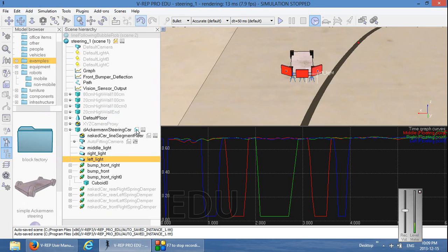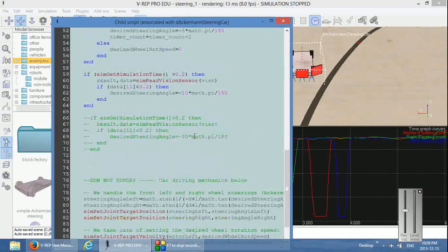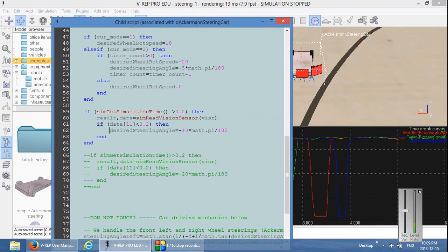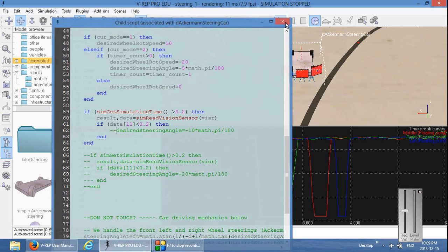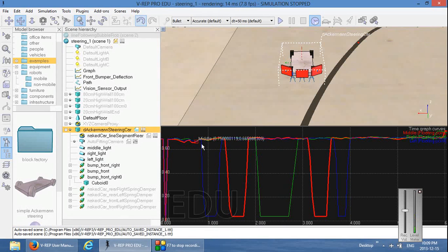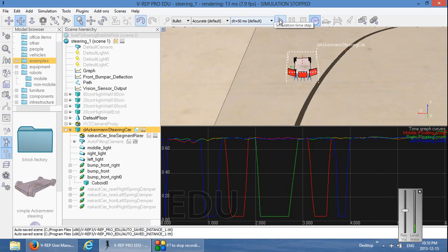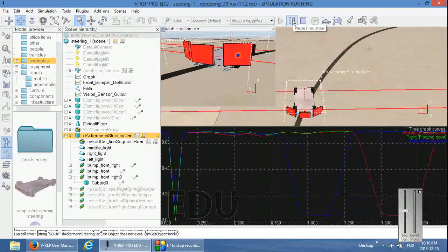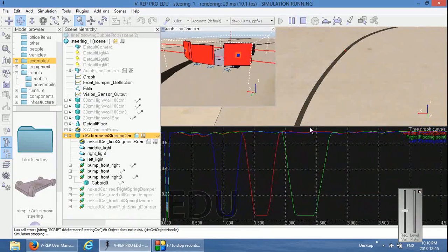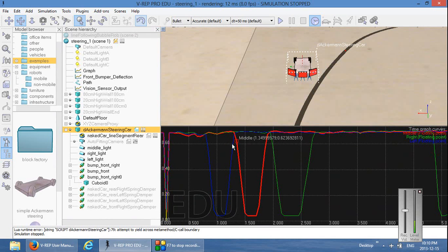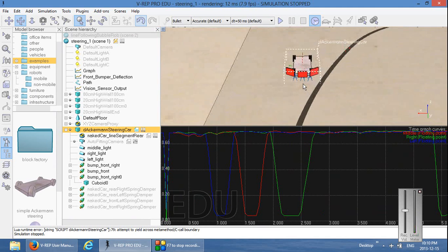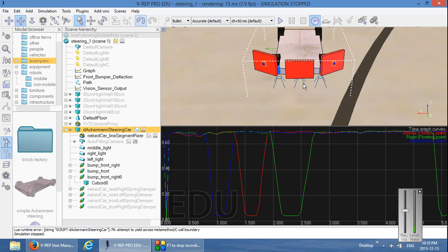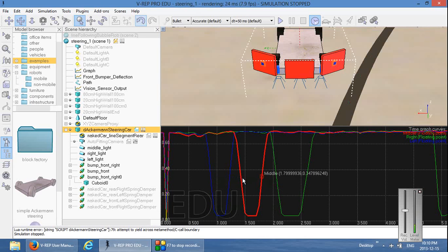Let me also temporarily turn off the steering angle. This is the average intensity values before we changed the sensors, and you can see that this is quite steep. Now when we drive over the line, you see that there is actually now some overlap in between the sensors. This is very good because now you can try to estimate the location of the line based on what the reading is and whether there is a combined reading.